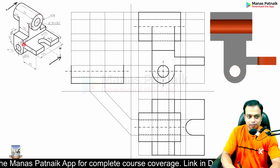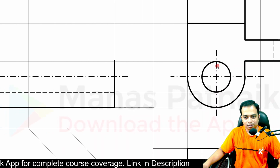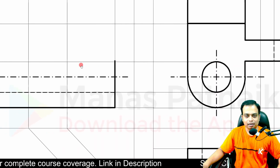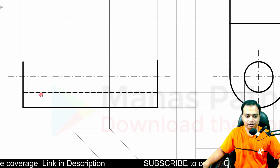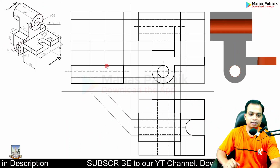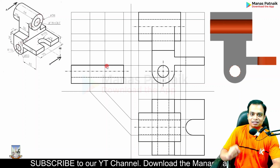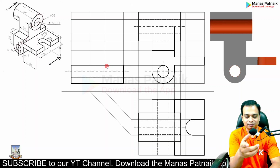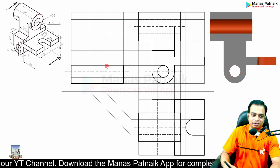Then, sir, one more thing. If you watch, there has to be one more hidden line, a dashed line. Corresponding to this, you've made a dashed line. So here also you should make a dashed line, but I haven't. The reason being very simple, not very simple rather. The reason is that the line thickness that I have given is 1.5. So try to listen to this. What is happening over here is that there is an edge.